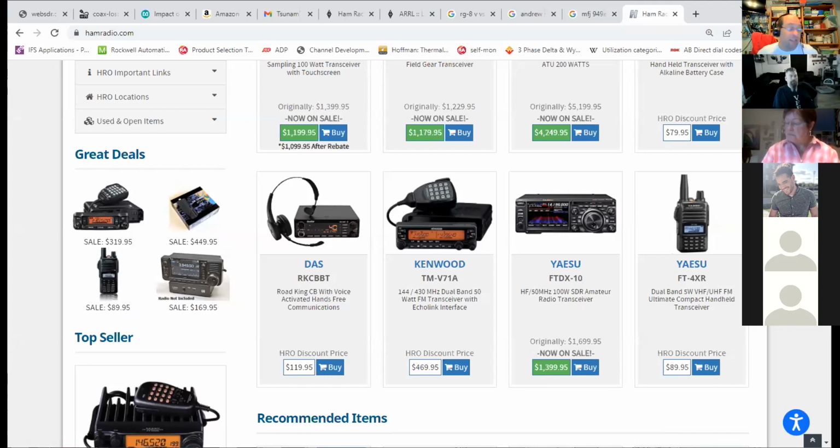Essentially, the chipset, it's a radio on a chip, right? An integrated circuit is a combination of a whole bunch of stuff on one chip. That radio and the Baofeng radios are built on the exact same integrated circuit chipset, which is basically a radio on a chip. They work remarkably well. But what they're not good at by themselves is rejecting signals that are not being listened to. So the Baofeng, which has minimal filtering, gets just hammered in an RF rich environment, whereas the Yaesu, because it has decent filtering, doesn't get hammered in the same environment.